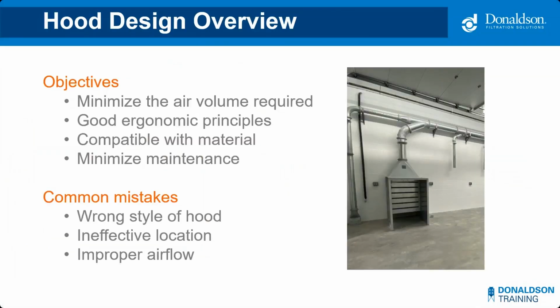So a well-designed hood is going to minimize the amount of airflow that's required to effectively capture and control the dust where it's released. And you'll hear that commonly, minimizing the airflow, and that's all because airflow equals cost. So if we can do an effective system at the lowest airflow, it's going to be cost effective both upfront and over the life of the collector.